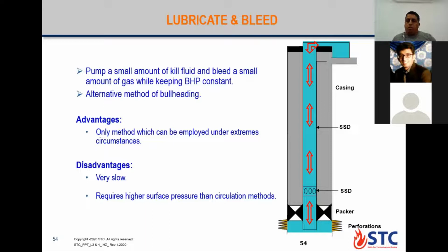Like you said, the lubricate method. When you shut in the well, you would be giving time for the kill fluid to segregate as a density difference inside the well. That the oil would come up and the kill fluid would go down. And in this way, you would fill the well with kill fluid, whose hydrostatic pressure would be more than the formation pressure. Yes. After each step, I repeat this one in maybe 10, 11, 12 steps.